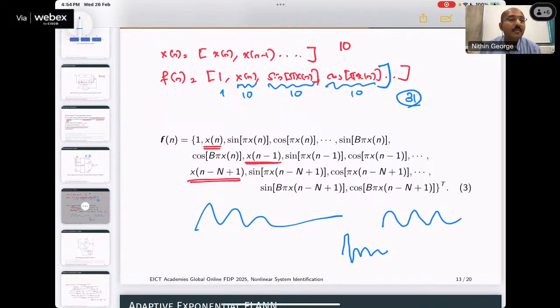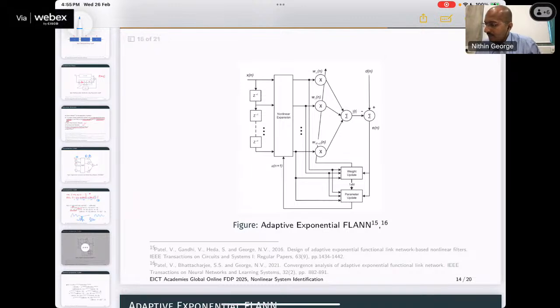exponentially decaying sine wave or an exponentially expanding sine wave, where you also have control on the way we decay the sine wave. Understood? So we have a change in the amplitude, a change in the frequency, and also a change in the way in which this decaying is going to be done. Then it becomes what is called an adaptive exponential expansion. So you are not using a sinusoidal basis function, you are using a decaying sinusoidal basis function, where the decay factor is also going to be estimated in every iteration, so that you get a very good approximation of this.